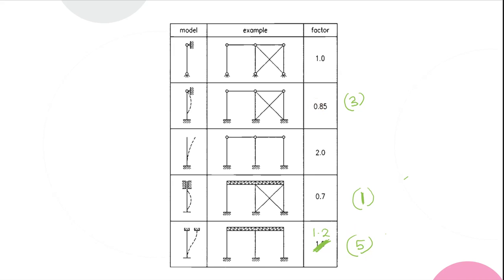Okay. This one I forgot to mention earlier, this is number 4. Number 4 earlier was the pin support for brace with unsway, this is number 4. So number 5, you can see it is unbraced. It is effectively held in position and direction at one end, and at the other side it says that it is effectively held in direction but not in position.